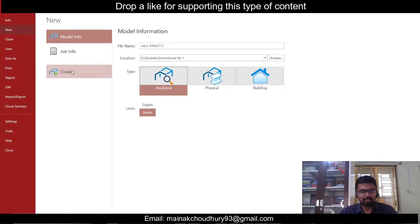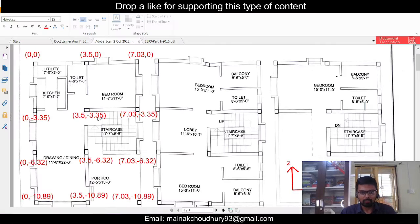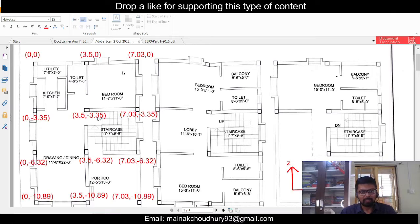First of all, we'll make the STAAD file here, and this will be created. So we have to insert the coordinates here. First of all, we'll go to our plan. As you can see, we'll just consider the main columns here to roughly check, and as you can see, I have marked the coordinates.